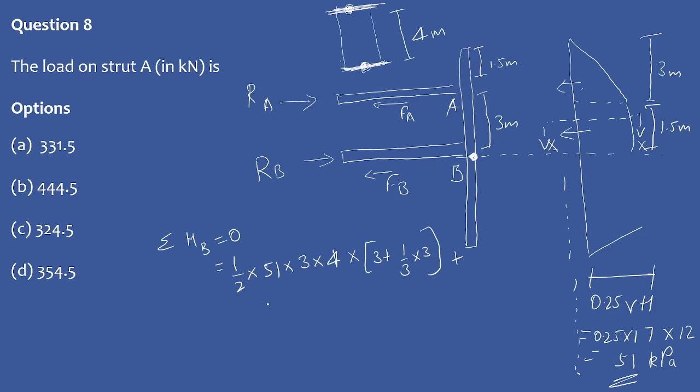Inside plane depth is 4 meter, and the lever arm here is 1.5 divided by 2. So basically we are considering from here, and since the nail B is located at B only, there won't be any component of this while calculating the moment, but we'll have the component of the nail A, which will have the reaction at A.